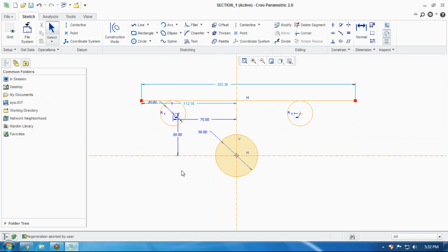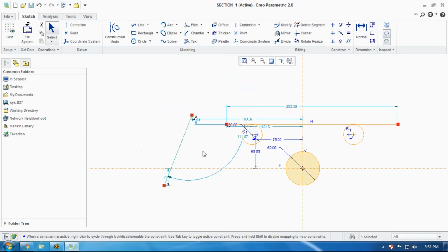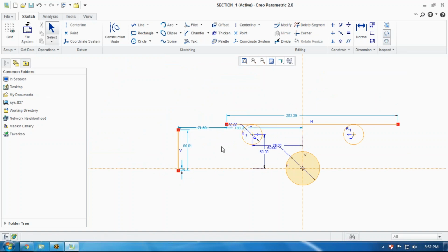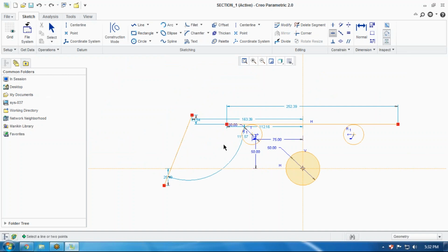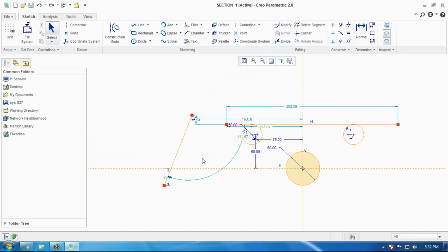They both have been touched like this, right? Now what am I doing here? I'm just going to create one line segment like here, but this is not vertical, this is not horizontal. I'm just going to create one line which is non-vertical and non-horizontal. I want to make it vertical first of all, so just go for the command called vertical in the constraint. Pick this line, this will be converted into vertical. And now if I want to make it horizontal, just go for the horizontal command. And now you will ask me why the size is getting reduced. Just because we haven't specified the actual size of this line.